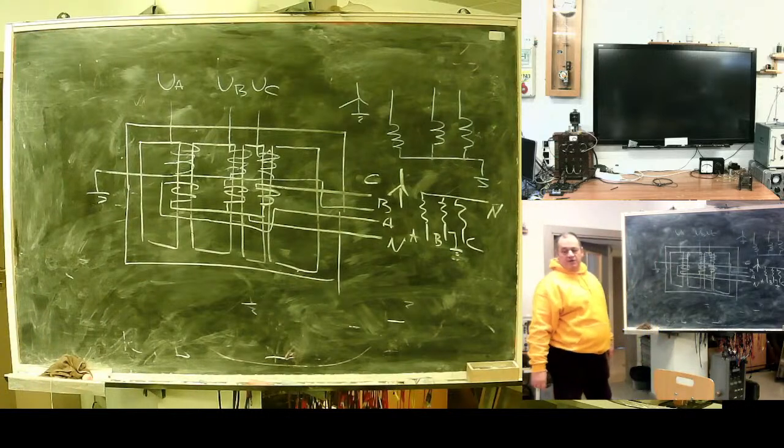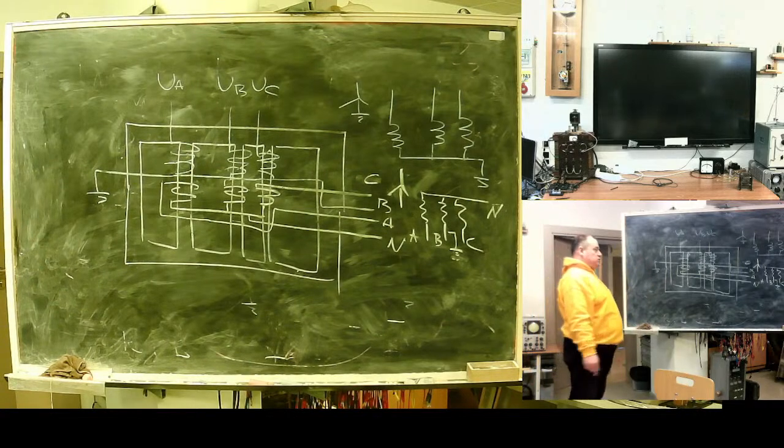Voltage transformers for distribution networks for many years were produced with grounded B phase, not the center of the star, to mimic the olden version of two transformers on line voltage. Don't be surprised.